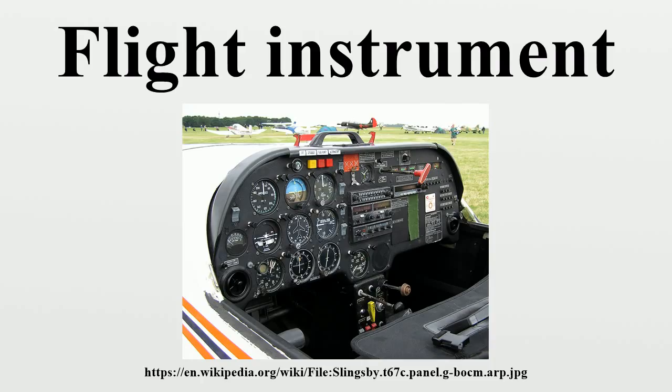Navigational systems. Very high-frequency omnidirectional range. The VOR indicator instrument includes a course deviation indicator, omnibearing selector, to/from indicator, and flags. The CDI shows an aircraft's lateral position in relation to a selected radial track.